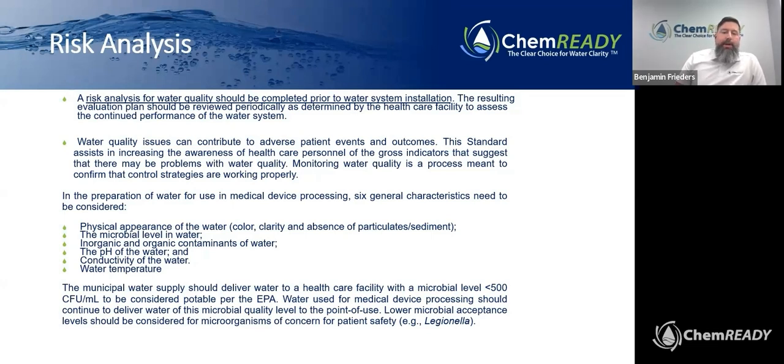Some of the characteristics for this risk analysis include physical appearance of the water, to include color, clarity, and absence of particulates, the microbial level in water, inorganic and organic contaminants of water, the pH, conductivity, and the water temperature. All of those have an effect on medical device processing itself. And the standard does go into pretty decent detail about how those affect each of the medical devices.